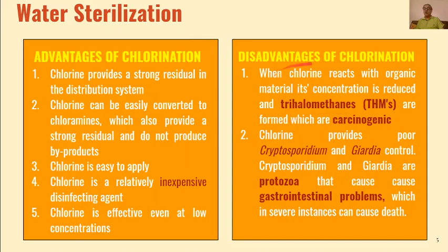So chlorination has a disadvantage in that respect, and this can be avoided if the pH of our system always remains more than 4.5, then no trihalomethane will be formed, and then chlorination will be an effective medium.